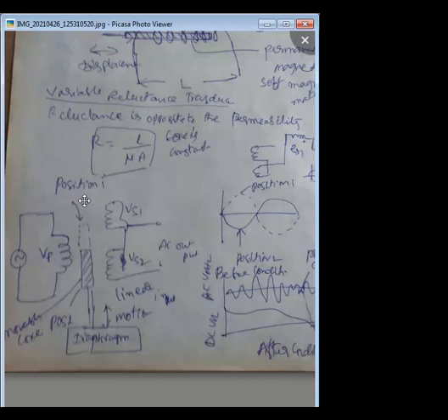If the core is moved to upward position 1, as indicated by the dotted line, the core is very near to secondary coil VS1, and most of the core is covered by secondary winding 1, but secondary winding 2 is not covered much. In such a situation, most of the voltage will be produced at VS1, and less at secondary winding 2. Due to that, the voltage at secondary 2 is less and the voltage at secondary winding 1 is higher, so we will get a higher voltage of positive value. The difference of E1 and E2 will produce a higher voltage.